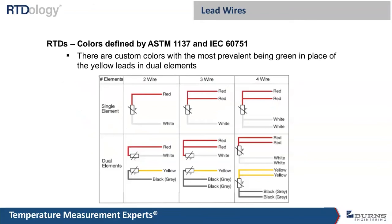Now, the international standards and the ASTM define the colors a little bit differently. So in the case of a dual element, you're going to see a yellow lead instead of the green. And there are several manufacturers that are still using the older color codes. So in place of these yellows, they're just going to be green, and it helps to know it's just a legacy thing. It's been around for 50 plus years, and they just haven't changed.